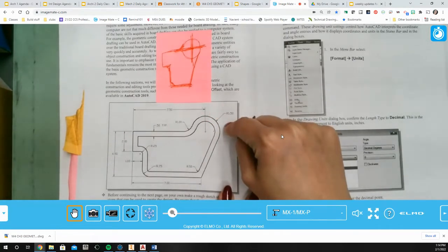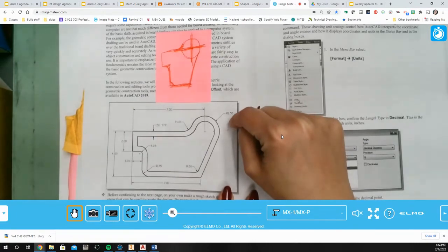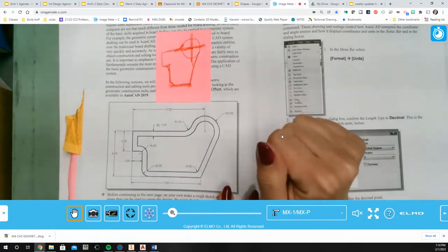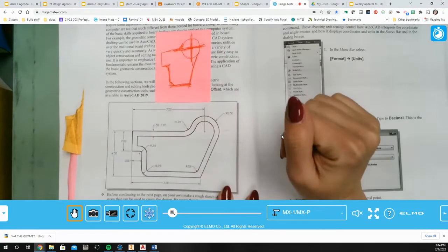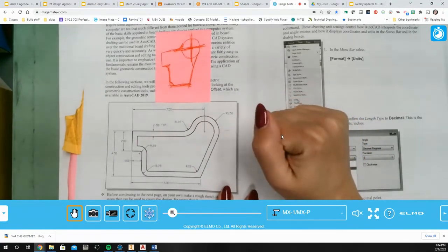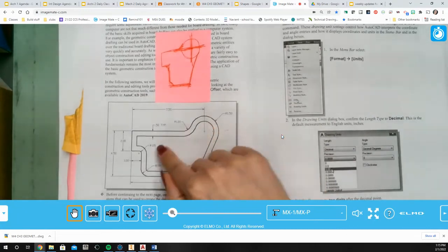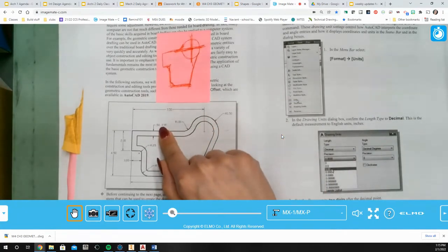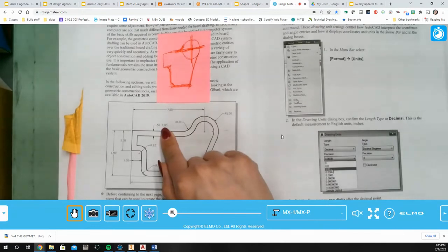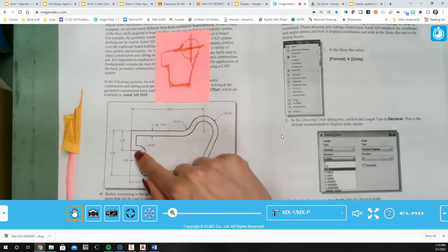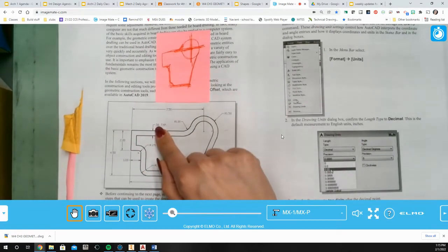You click on it. Do you want to turn it into one? Yes. And then hit enter and select all the lines to join them together. And then I would offset it to the inside by that 0.5. See that TYP there? TYP means typical. It means that all of these thicknesses all the way around are 0.5.